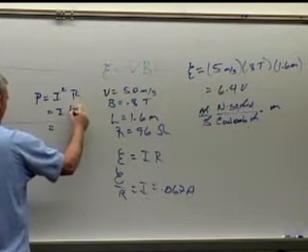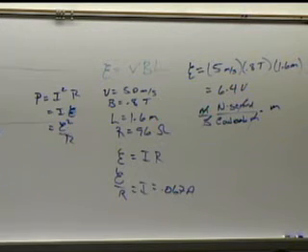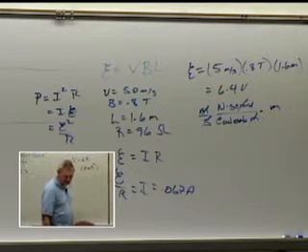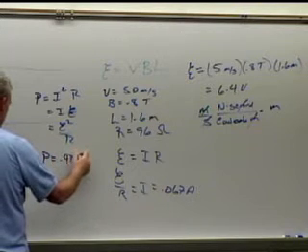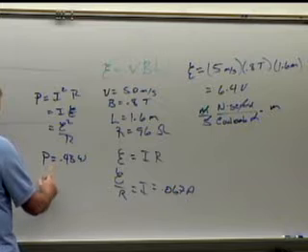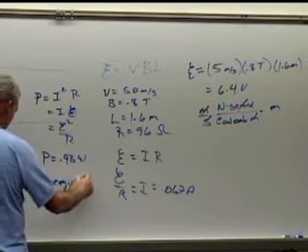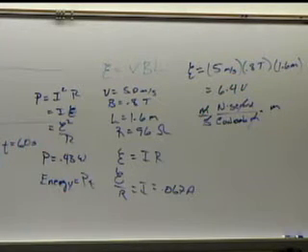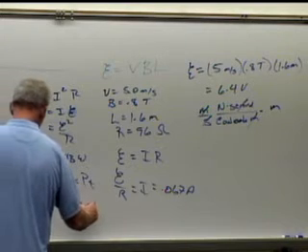Let's go ahead and change that V to this. And we could also do this. Any of those will work. And so you come up with power is only 0.43 watts. And then the energy that is burned up, or that is used, or that is required, the energy would equal power times time. They told us the T was 60 seconds. So you just take this 0.43 watts times 60 seconds, and you wind up with, you've only burned up 26 joules.